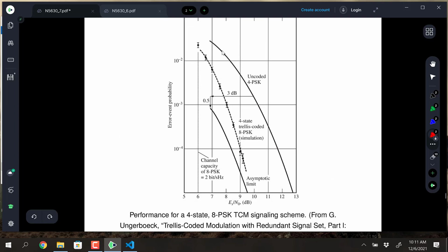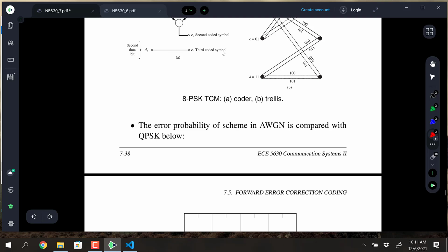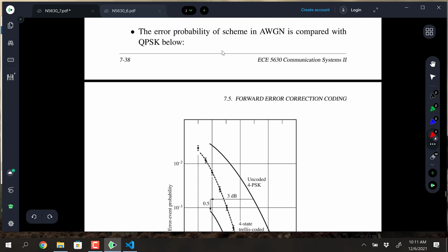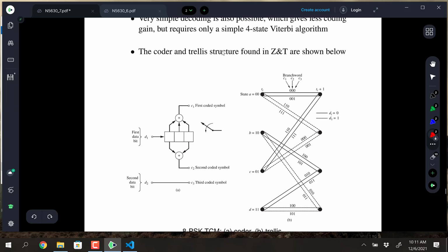They're finicky. They get extremely high coding gain, but they have thresholding phenomena. So the waterfall curve of a turbo code is like a step function. It comes out and just goes way down. But depending upon how this iterative decoding works, it can have floors in it where it doesn't drop as low as what you'd think. So there's things that I learned from being on his dissertation committee about turbo codes.